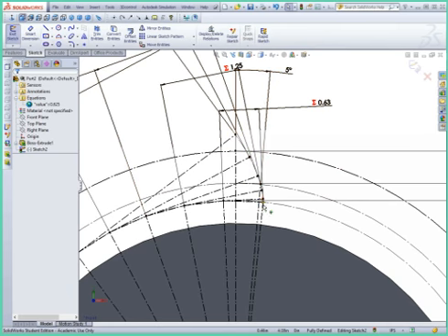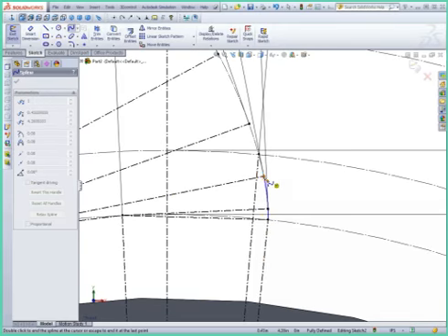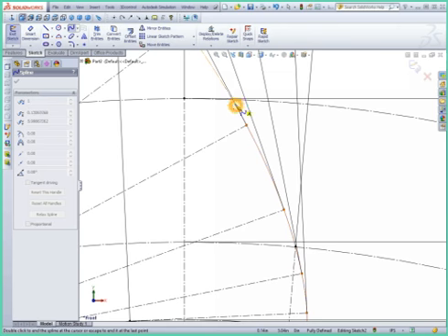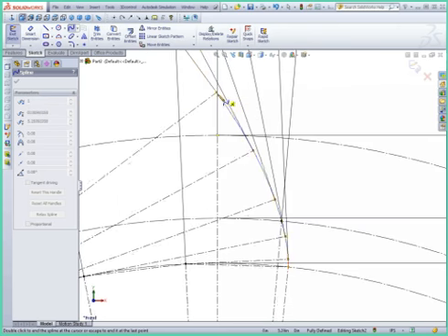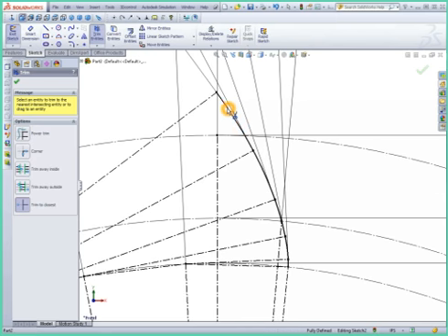The last thing to do is just to draw the tooth relative to this spline. So we select the spline tool again, and we click on the points that we want to draw. Here we don't actually have a point yet, so we can click on this last point and trim the end.